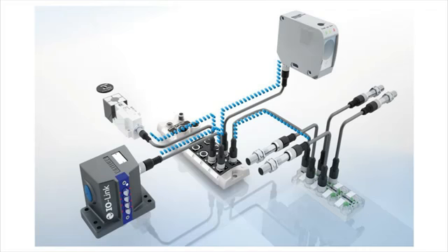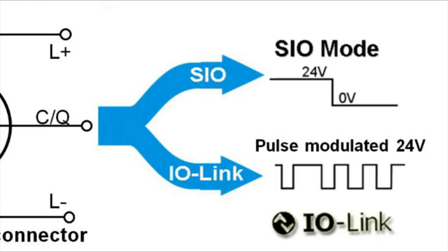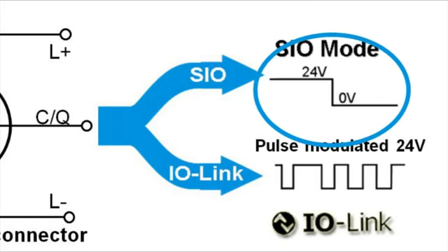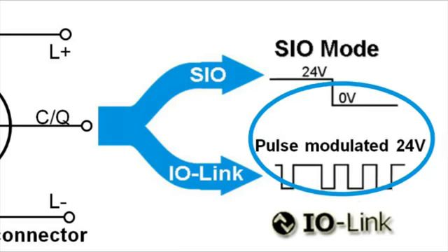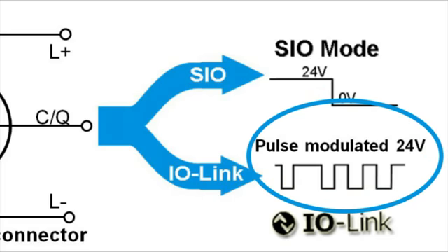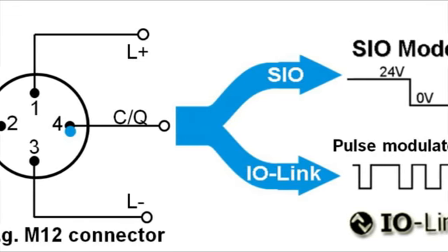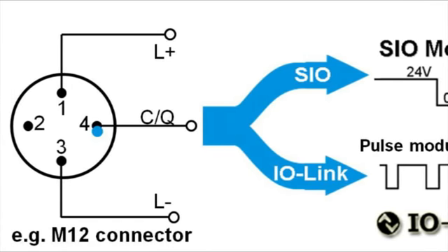IO-Link is not a new bus system. It is a serial bidirectional point-to-point connection between IO-Link master device and the sensor or actuator. IO-Link transfers the well-known signal technology of binary signal interface and, as an add-on, can transmit I/O data via serial protocol. It eliminates the bottleneck between the sensor and field bus level by making today's binary standard sensor interface capable to communicate.